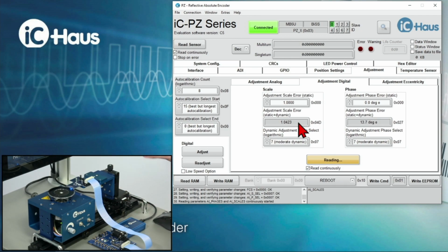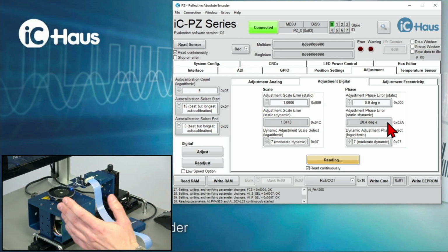For the X manipulator or the tangential alignment on the right side, you can see that we are still a bit far away from the 20 degrees, which are our target value. And again, I'm turning the micrometer screw here, the manipulator, and as you can see, we're coming close to our 20-degree target value. And what you've done now is somewhat set up like a golden device to start with in the lab, because this is really close to an ideal position.